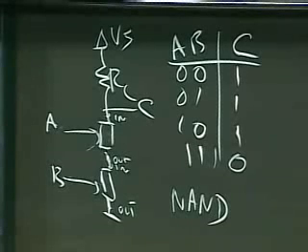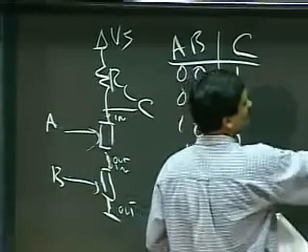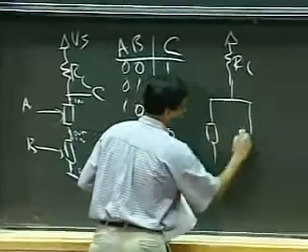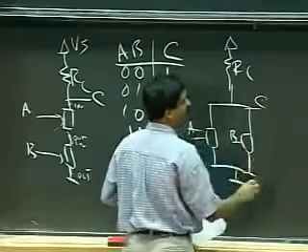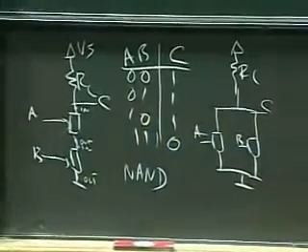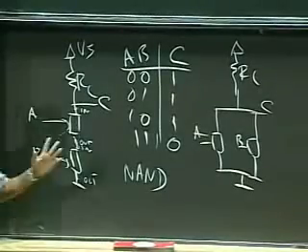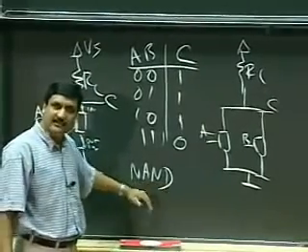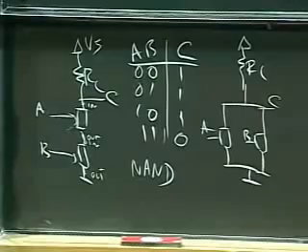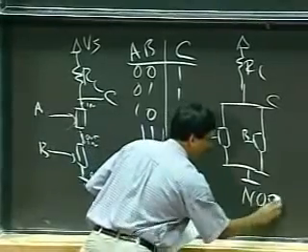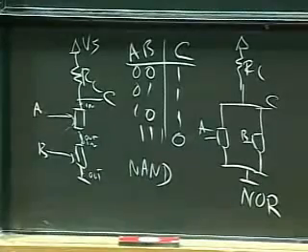This is unbelievable. 5 lectures and you've already come all the way from nature to the primitive building blocks of microprocessors. Pretty amazing. Okay, so what about this one here? What's this? I haven't told you this before, but if series becomes an AND, this is kind of an OR arrangement. What should an OR become? It's all completely logical.